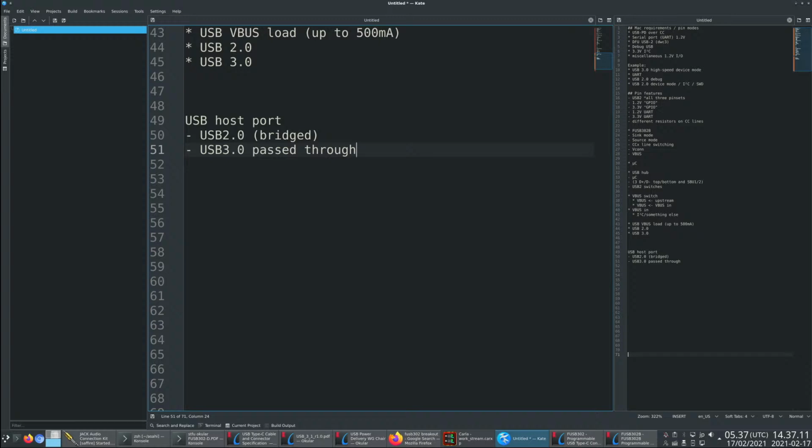But there's signal integrity issues if you try to use jumpers for this, so I should probably avoid jumpers. But I think a couple of resistors, or 0 ohm resistors, or sort of resistors with a cuttable link inside is probably going to be fine.